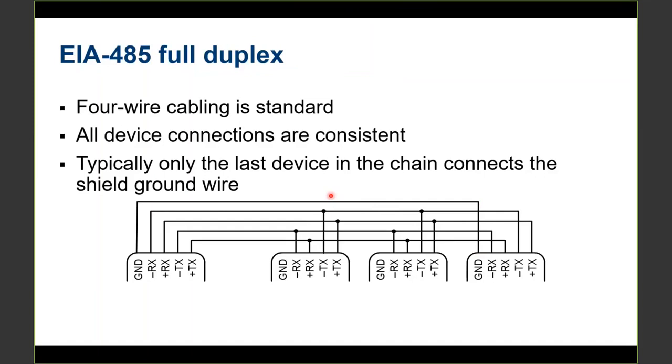It's almost like, kind of reminds you of tinfoil if you ever see these cables. So it's almost like they're wrapped in tinfoil all the way around that cable, and at that remote end, there's a connection to that metal or foil. And it's a wire that's landing, and it will land on this ground, and that's a shield ground over here.